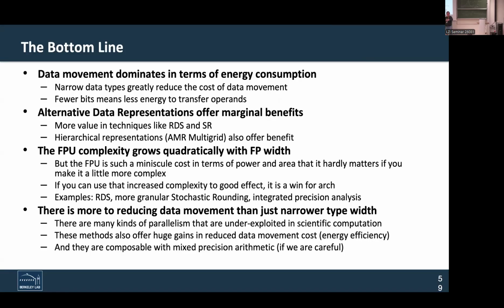One argument in favor of stochastic rounding would be that you have the internal data with 32 bits, so why would you round it? But maybe you want to put the data in 16 bits for storage reasons. That's what we're talking about: the ALU can be wider internally, and I use that extra information to make a more informed choice about whether to round up or round down.